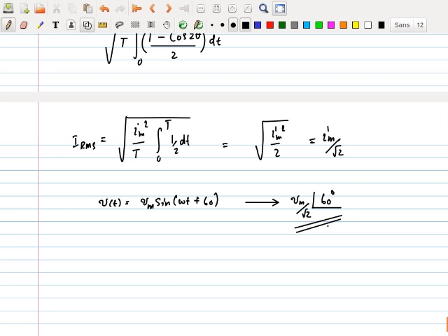Right? In my circuit. So if somebody comes and tells you there is 200 with an angle of 40, let's say somebody gives you a circuit with 200 at 40 and asks you to draw the sinusoidal waveform, you would do what? You would say, oh, okay, if this is the case, this is going to be equal to what? 200 times root 2 sine of omega t plus 40. See? That's how you would look at it. If somebody gave you this, that would have been the original waveform. If you know the original waveform, I can move it into RMS in that manner.